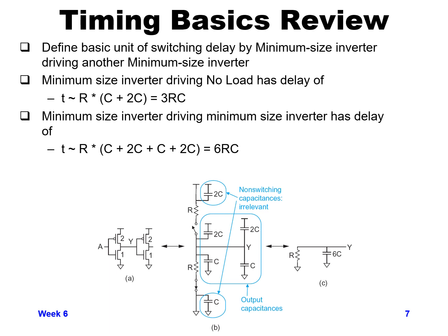The equivalent resistance of the PMOS and NMOS are both just a value of R, because the PMOS was 2R divided by 2, so it's just R. So the propagation delay of rising or falling is going to be proportional to R times the C value of the drain of the NMOS plus the 2C value of the drain of the PMOS. So that's proportional to 3 times RC.